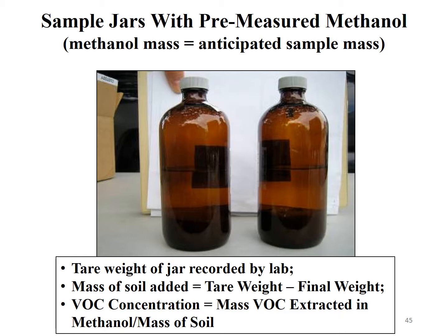Methanol is the preferred method for collecting MIS samples. Most labs consider that the gold standard amongst the options that are noted in method 5035. There are other allowable sample preservatives in that option, but we encourage the use of methanol whenever possible. Again, when the samples are put into the methanol, then the VOCs are immediately preserved there and captured, and that's what we recommend.